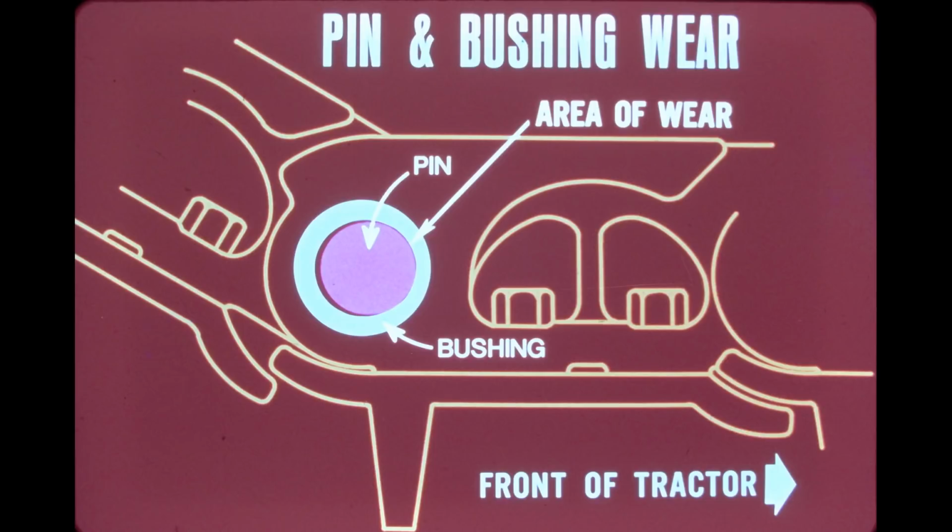The gap created between the pin and the left-hand side of the bushing wall is the result of the pin and bushing wearing on the right side. This one-sided wear on pins and bushings allows the pins and bushings to be turned or rotated 180 degrees in the chain to bring unworn surfaces to the working area. Turning the pins and bushings is required when the wear in these components allows the track to stretch beyond specified tolerances.